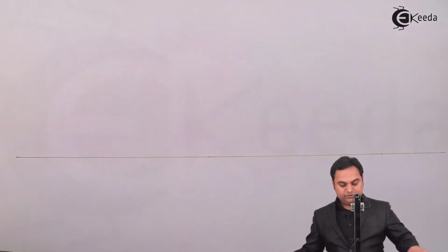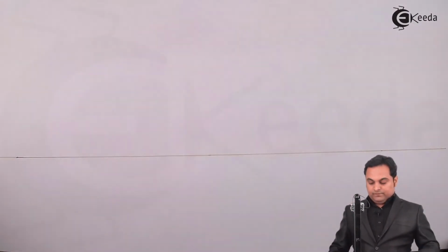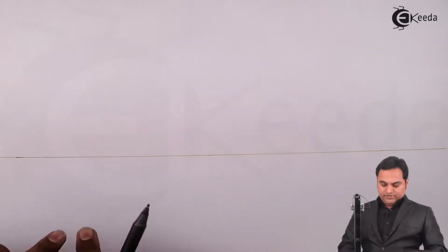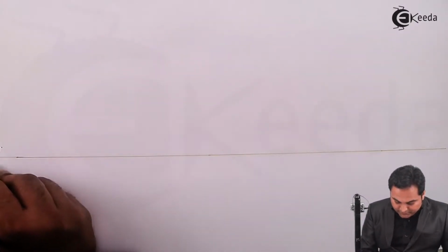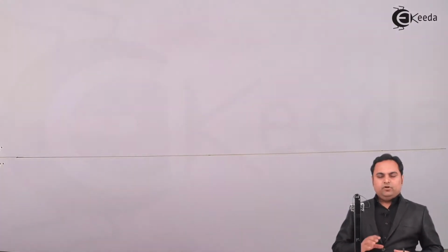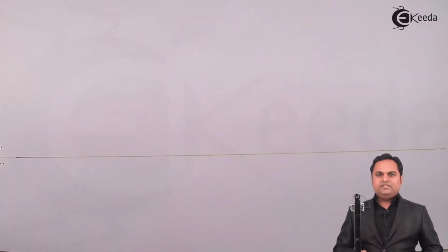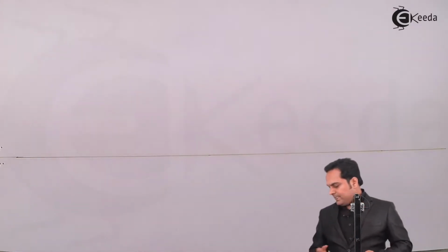Here I am drawing a light horizontal line first. Next, since the square pyramid has to be tilted on its triangular face, here I am drawing the square in HP, because we have this as VP, vertical plane, and here HP. When the triangular face on which it is resting is in HP, it means the complete square pyramid is in HP. So when we are looking from top, we should see the square of side given as 40 mm.